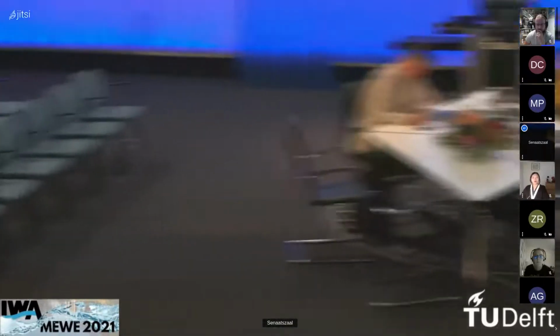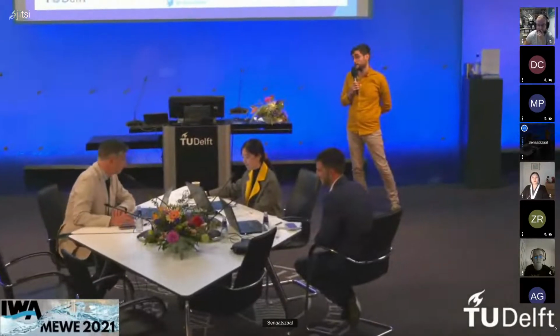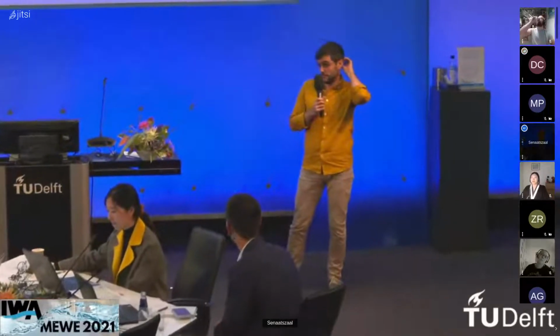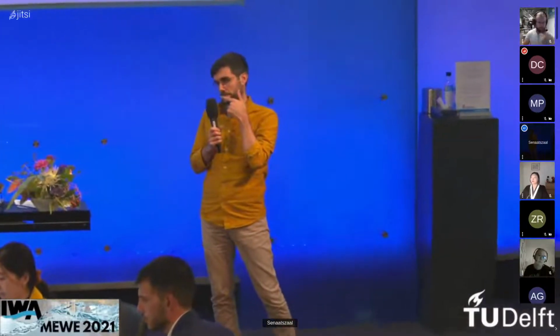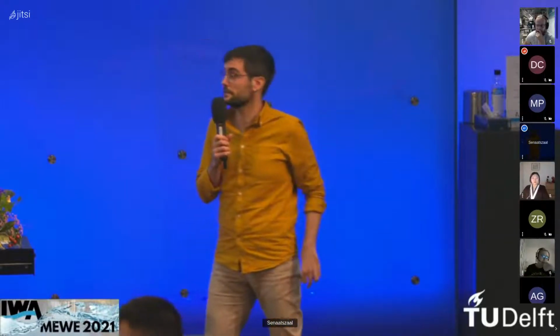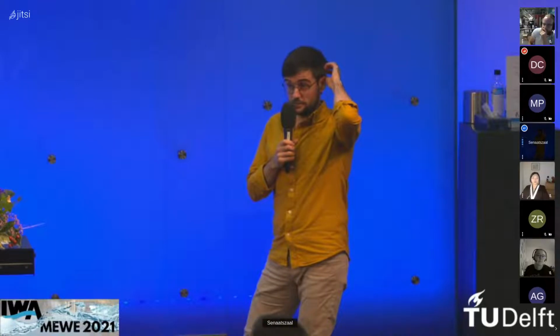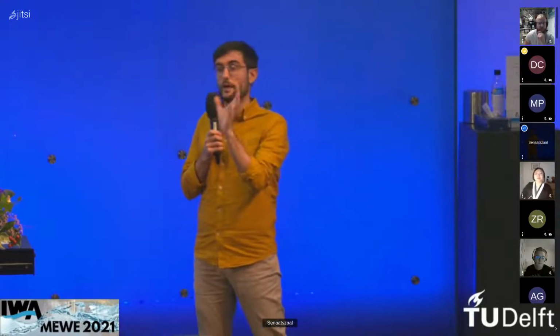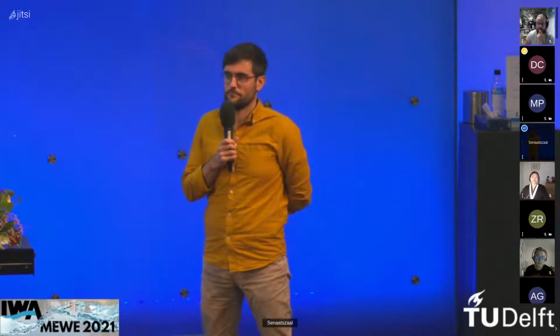Hello. Yeah, it depends very much on the plant and mainly on the concentration of iron. So the clogging is partially because of the iron that's precipitated and also partially because of the biofilm that grows due to the conversion of mainly ammonia. But iron is clearly the main trigger or the main reason why backwash is needed. If the plant has a high concentration of iron, up to 30 milligrams per liter in the Netherlands, then you need to backwash every day or every couple of days. But if the concentrations are low, which was the case of this one, I think it's every week or something like this. Okay, that's pretty quick. That's quite often, but you still see quite a clear difference in the protein expression then.